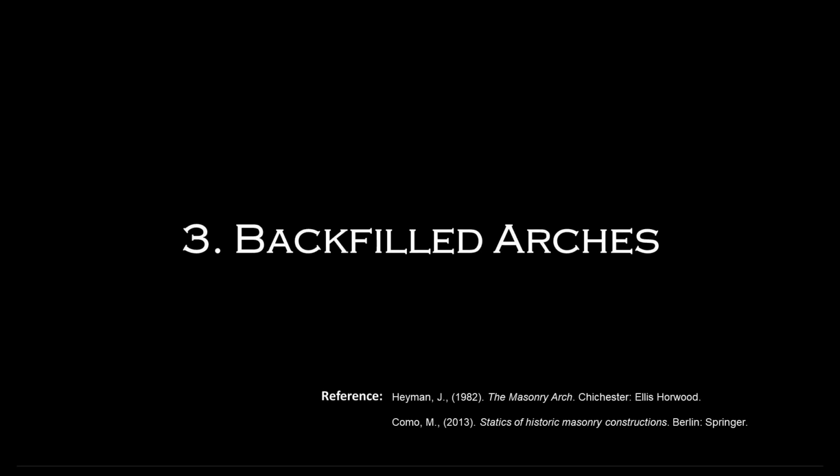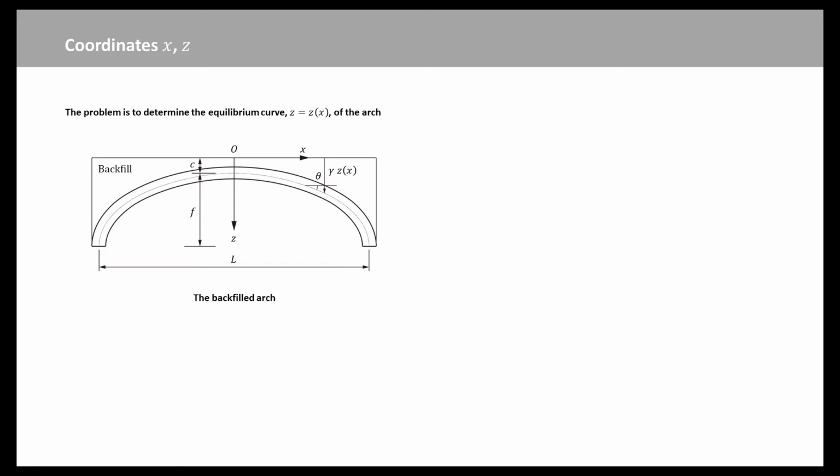In addition to the weight of the arch, there are also the weights of the filling material, the spandrels, the road bed, and any ballast, which as dead loads should be taken into account in the arch design. This problem was studied by Inglis in 1863. This figure shows a voussoir arch supporting a level roadway. The fill is supposed to be of uniform density and to impose a purely vertical load on the arch ring.